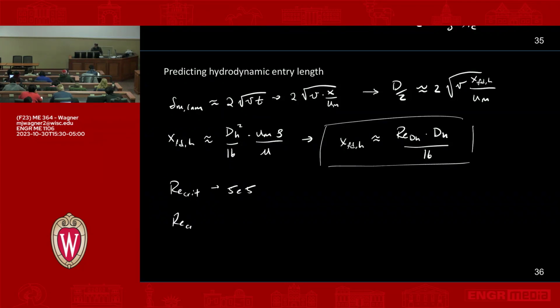So Re_crit in terms of d_H is often about 2300. From fluids, you probably recognize that. What this is saying, and we'll get to this in more detail next time, is if flow comes in and you compute the Reynolds number of the flow coming in in terms of d_H, and it's above 2300, it'll be turbulent. Otherwise, it's going to be laminar.